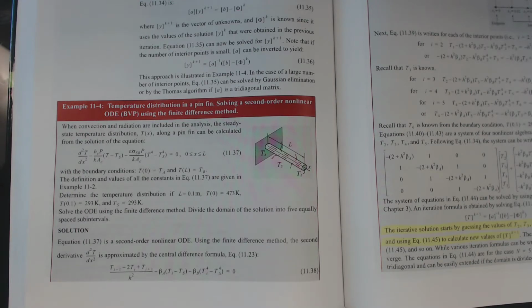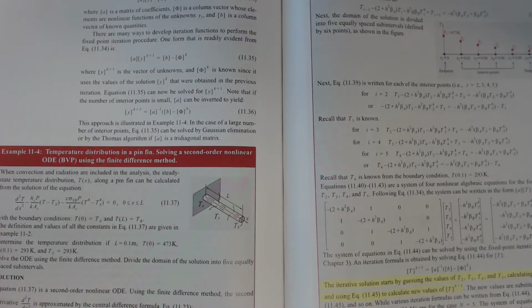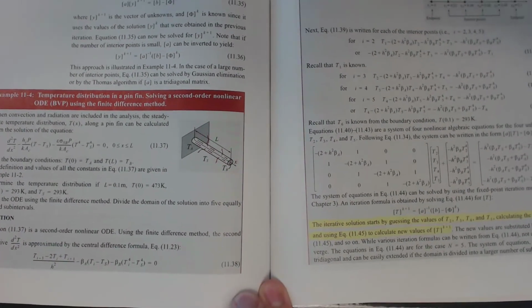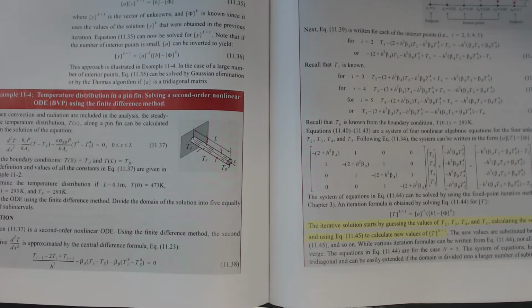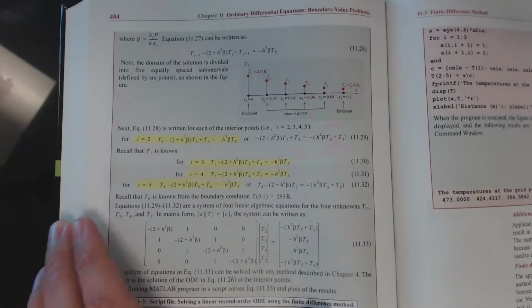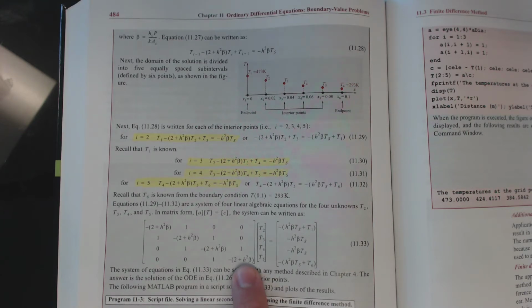So this has one distinct implication in engineering education that a lot of students have seen but not yet understood why. Finite element solutions in many common CAD programs. I know in SolidWorks, whenever you are pursuing a solution for small displacements, small deviations, small deflections, in general, FEA solution methods are able to keep things linear.